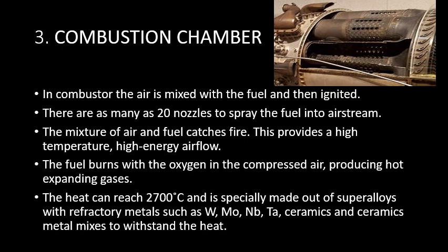For that reason, the entire combustion chamber is made out of super alloys with the refractory metals such as tungsten, molybdenum, niobium, tantalum, ceramics, and ceramic metal mixes to withstand the high heat.